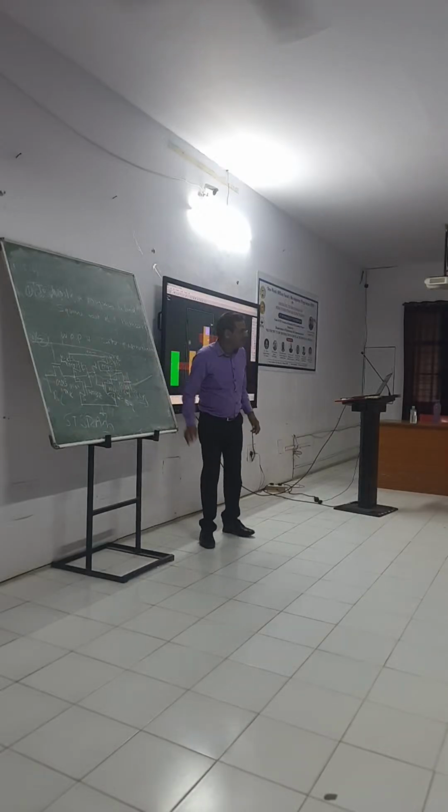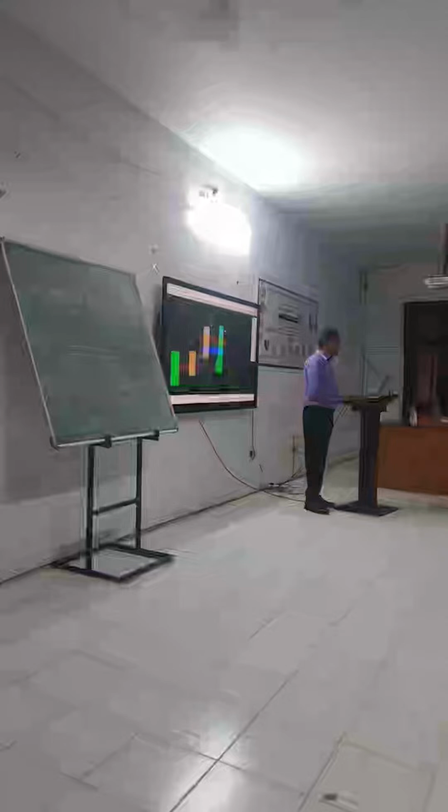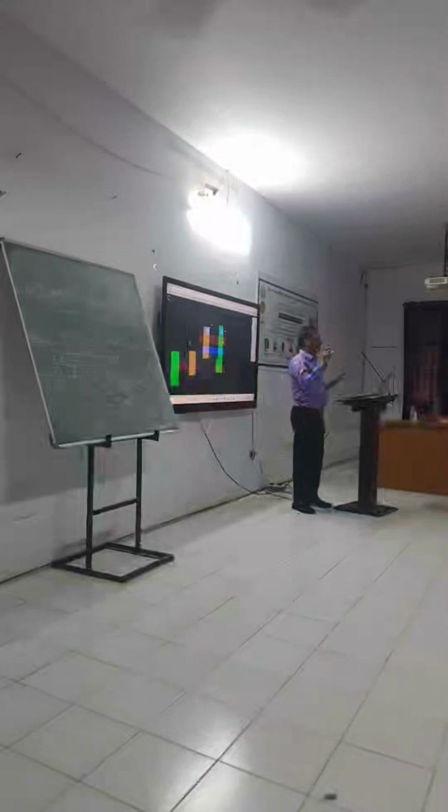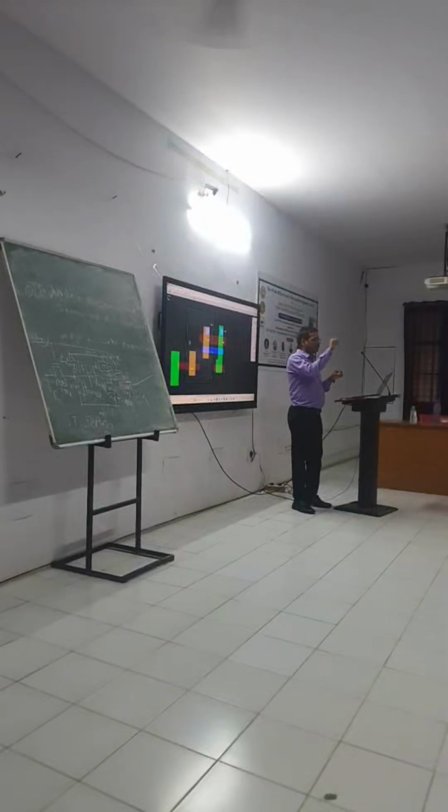Now see, on this side, the other side, another MOSFET is there. Its name is MN4, and here its width should be more. So the other PMOS I will draw here, and it is 1.5 times the width. So this is the other MOSFET. Here I'm just crossing this polysilicon. It is not an exact measurement. Measurement should be proper, otherwise area will be more and errors will come. So that one I am not taking right now, just a rough idea of how you can put the device.